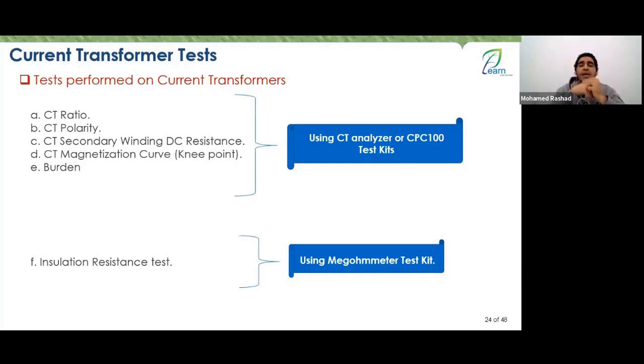And it might be just in the reverse direction or non-directional. A reverse zone, for example in distance protection, can be used as backup protection in case of bus bar failure or the feeder connected with the same bus fails to open. And that's why this polarity was very important.